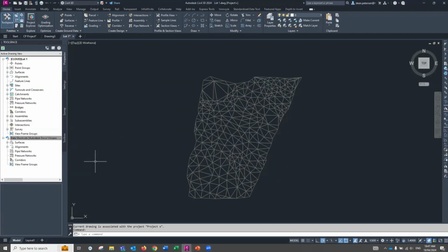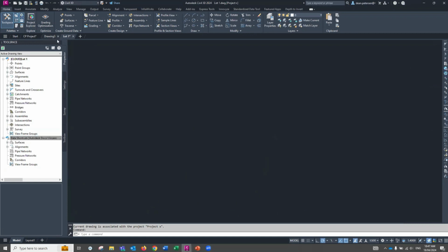All right. So what I'm going to do now is turn that off for a moment. Don't want those coming up. And we can go back to our new drawing. Now, the other thing you need to know is before you make data shortcuts in your new drawing, you need to save this new drawing up on the cloud.